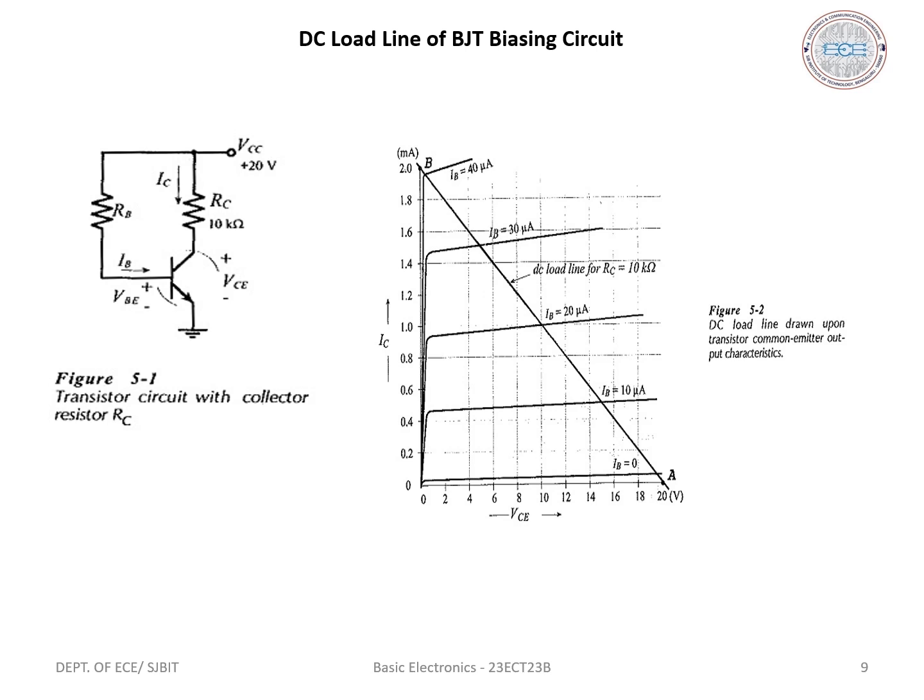To draw a straight line, consider two different conditions. Put IC equals 0, then VCE will be equal to VCC. If you put VCE equals 0, then IC equals VCC by RC. From this equation, we can obtain a straight line on the output characteristics curve of the transistor circuit with the two extreme points being (VCE, IC) equals (VCC, 0) and (0, VCC by RC).